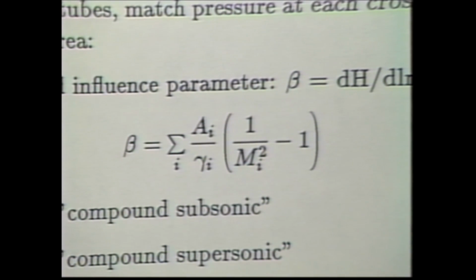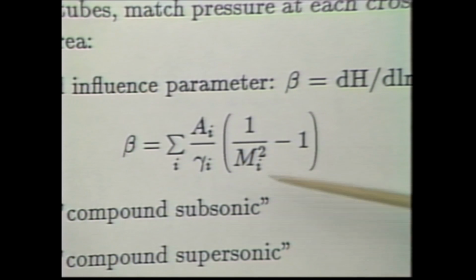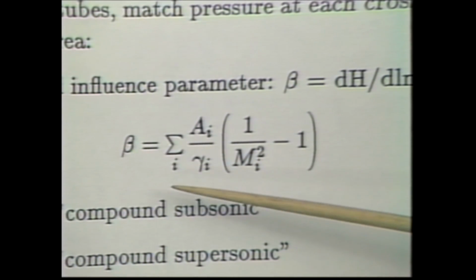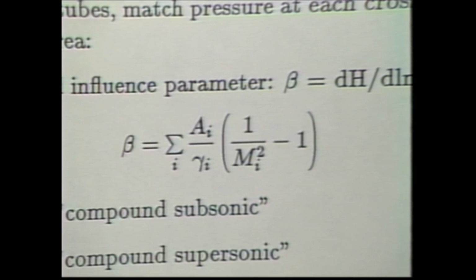In other words, even if the boundary layer is relatively modest size, because of the sensitivity of the net performance of the flow to the inverse square of Mach number, that boundary layer can change dramatically the nature of the flow inside the engine. In other words, the way the flow responds to changes in area, or the way the flow responds to heat addition.